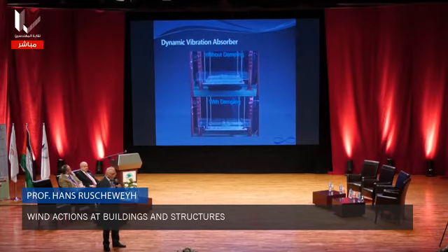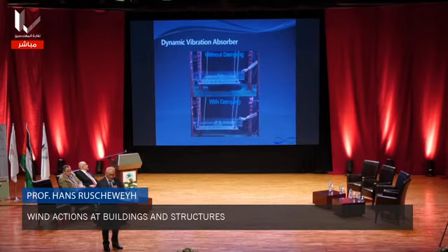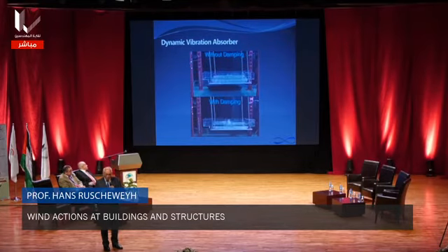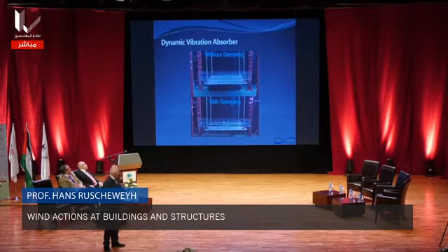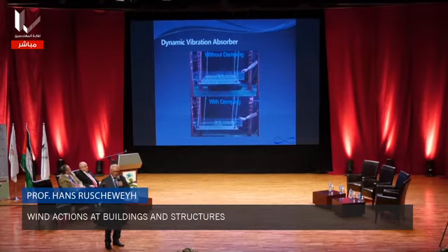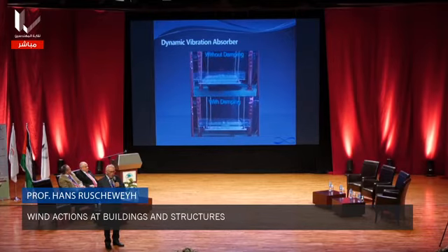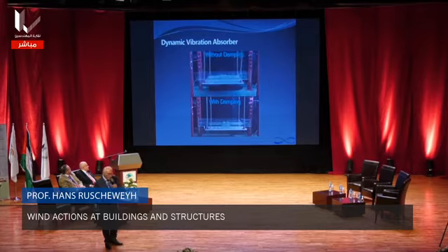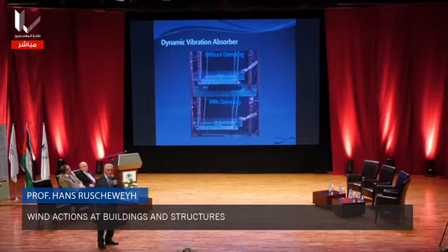The only condition that must be fulfilled is that the box must have no hole that the liquid can flow out of. It must be very well welded. This is the only condition, and you have no maintenance. You build it into the buildings or the structure or the stack, and you can forget it. We started with this type 20 years ago, and they are still working. It's a very simple system, and we use it very often for steel stacks.